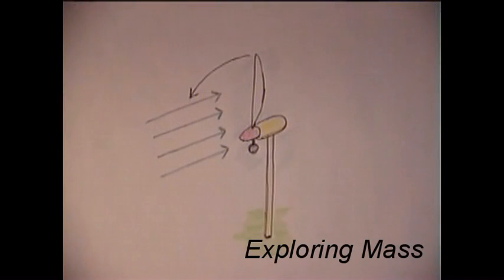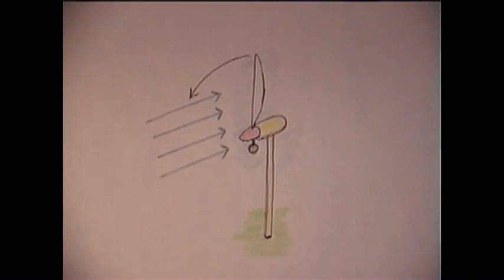The best rotor to do this, in theory, would have a single aerodynamic lifting blade. By contrast, a wind turbine rotor with 10 blades or more is generally considered a bad design to generate electricity with. A rotor with, say, 20 blades would be too heavy, have too much aerodynamic drag, and it would turn too slowly to generate much electricity. A single-bladed rotor can capture more wind energy and generate more electricity than a 10-bladed or a 20-bladed rotor can.